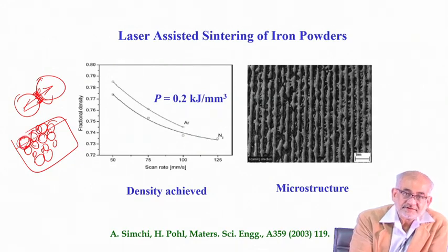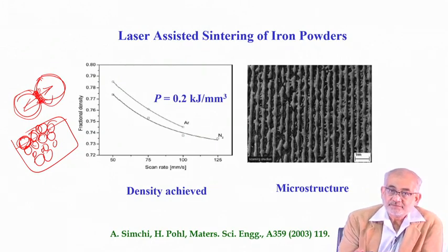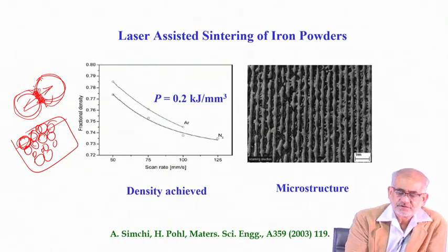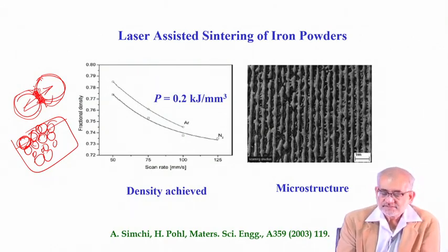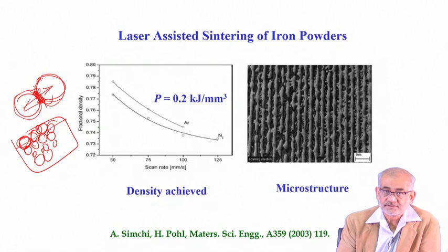The heating effect will be maximum at the surface, and hence the powder particles will get heated in such a way that a thin layer from the surface reaches a fairly high temperature that allows diffusional bonding to form. It can be solid state, or it can be formation of a thin molten layer, so liquid phase sintering, and this thin layer may form because of a eutectic reaction at the surface. No matter what, using laser, one can start with powder particles, sinter, and create a bulk solid, the density of which could be close to the theoretical density.